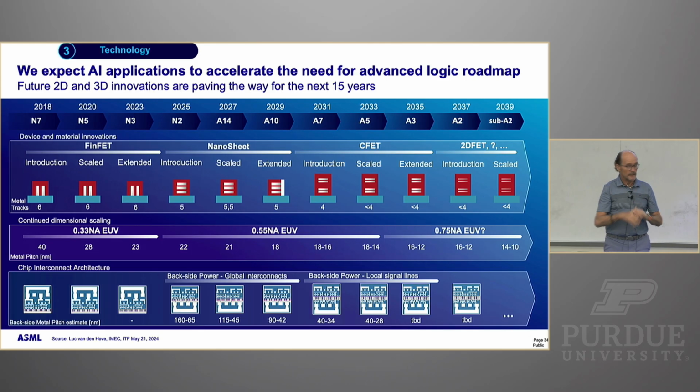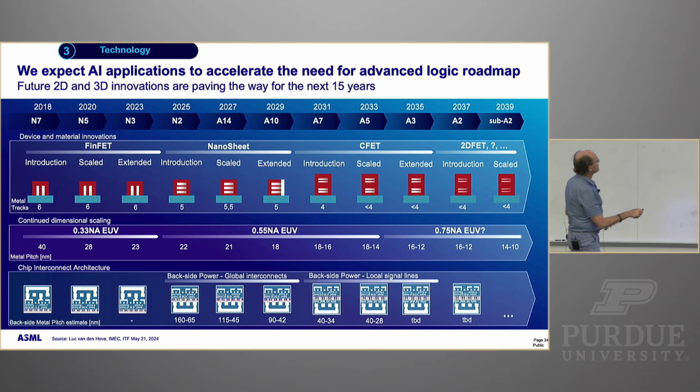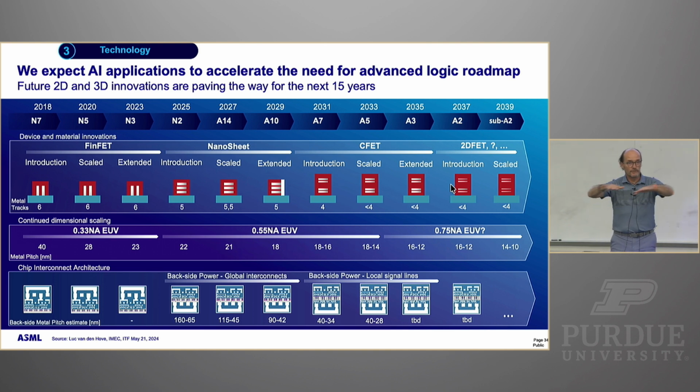That would be cool. So what we're now looking at is, can we actually make intrinsic 2D materials, like these graphene sheets, where electrons only move this way, and therefore they would only scatter here, instead of moving in all directions, and if I make it thin, there's always an interface close by, right? So a 3D material that gets very thin, the mobility suddenly collapses. Or at least that's the fear. There's also some new results that might not always be the case.